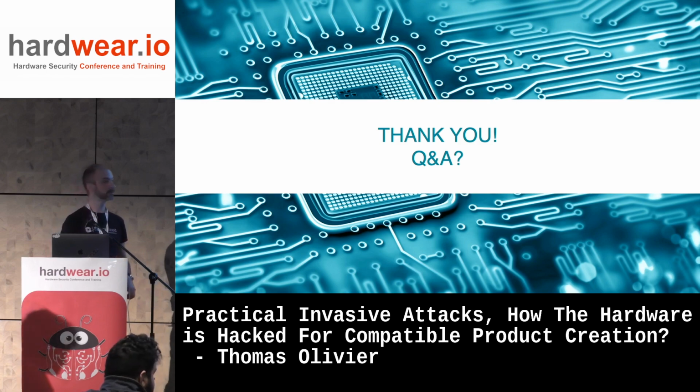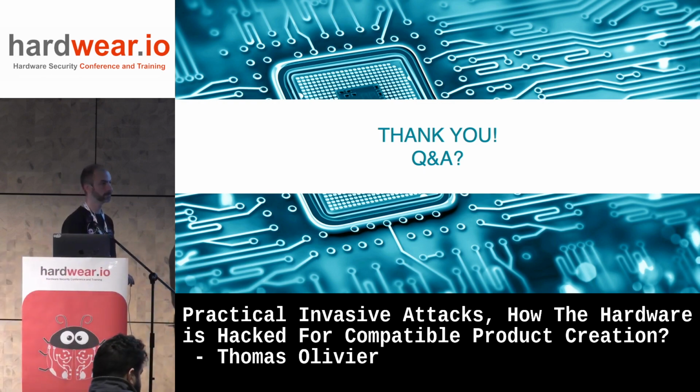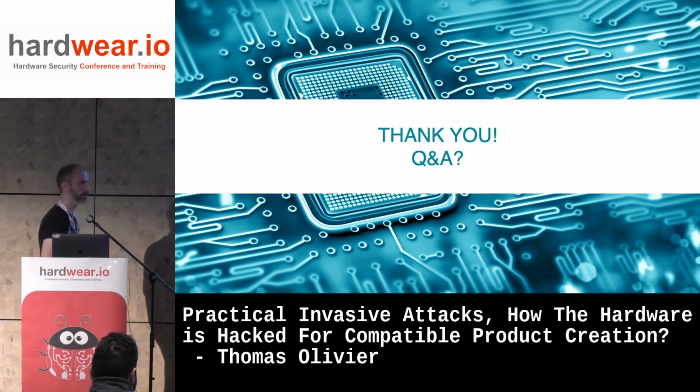Hi. I have one question. Once you got the full netlist of the chip essentially, is there anything stopping you from converting that to some hardware description language like VHDL? That's what we do. The netlist that I'm using here, that's VHDL. Okay, so you already converted it back to VHDL. Yes. So on this example, you have the digital logic as a VHDL block, but the RAM is another one, and they are speaking to each other. Okay. So then you can simulate the whole. Yes.